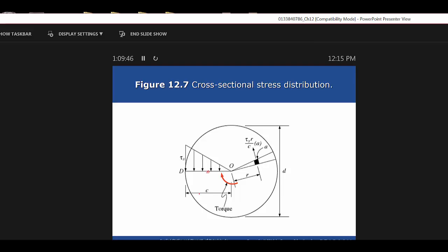You know what, that would be a good thing that you would probably want to punch those numbers into your calculator and make sure you can get that value. It comes out as 0.1071 meters, and then they just change that to millimeters, which is just moving your decimal point 3 places to the right. So 107 millimeters diameter. Now, the last part of that said select a shaft diameter to use.